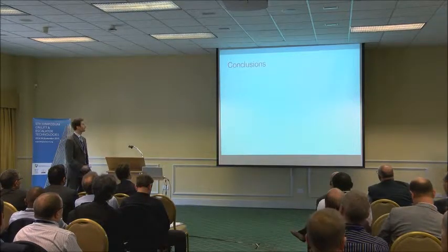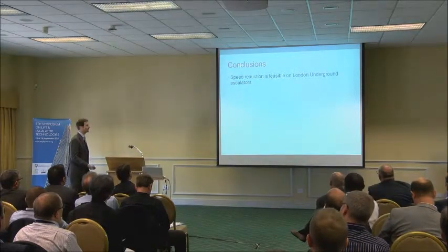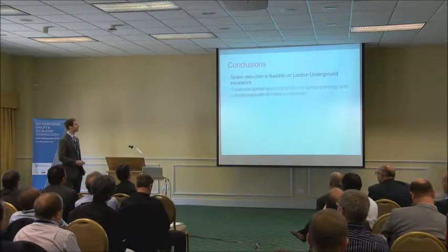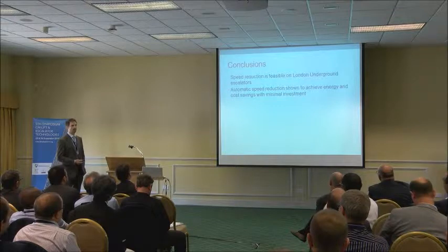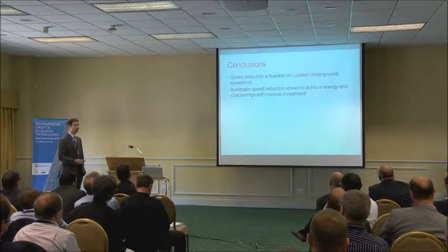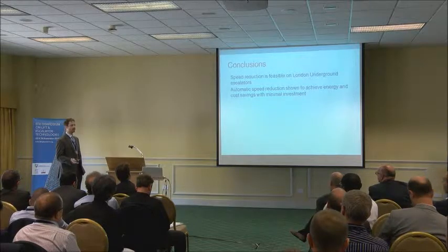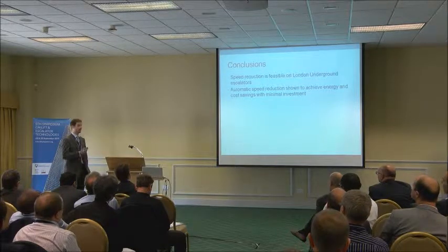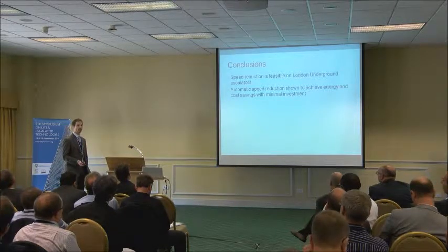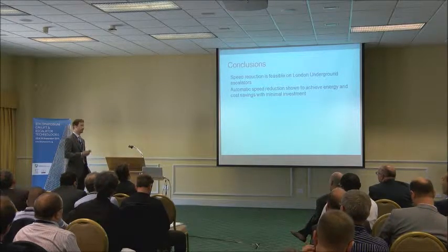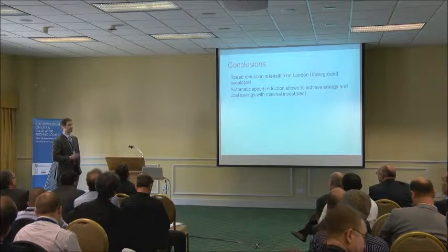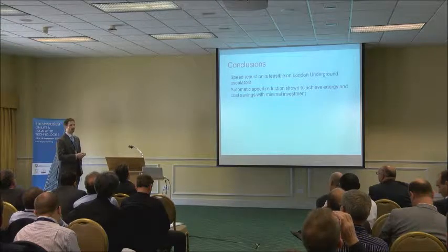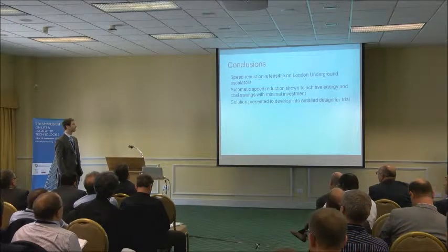So just to conclude, I found out speed reduction is feasible, which I expected to be the case, but now there's some figures there to back it up. And it's been shown to achieve energy and cost savings with relatively minimal investment. Something I didn't mention is that the controllers we already have have the capability of reducing the speed with VVF drives, and also have regen capabilities. So that will allow, when the repeated deceleration and acceleration happens, some of that energy to be regenerated. The actual amount of that would require some testing, hence the proposed trial.